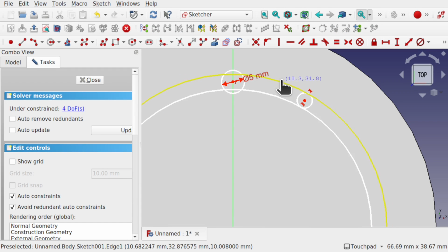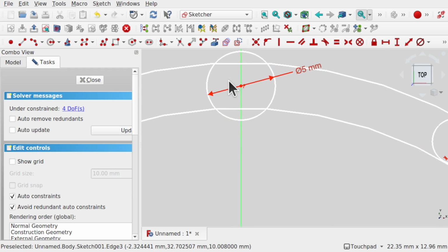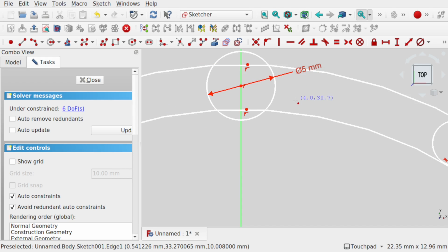So that sets some dimensions in here, and we'll use the 5mm for the screw head and bring this down. And you can see what we need to do. We need to think about the diameter of the shaft of the screw and have this symmetrical over these two lines. That's quite easy by using a point. Let's use a point, go to constraints on, and let's constrain it to inner circle and 1 point to the outer circle. Also going to hit the escape and constrain this point to this line, point on object constraint, and do the same with this one.